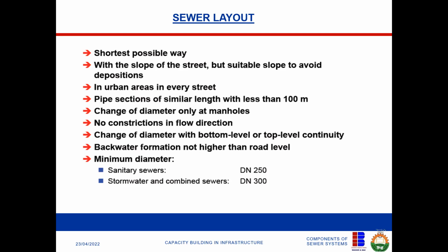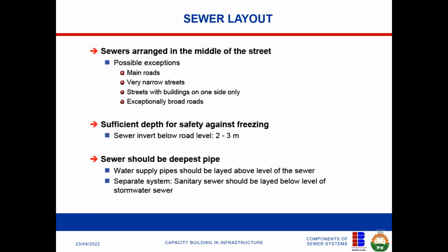You know, sewer has tissue papers, human remains, different nonsense you can find there. So you should make sure that anything that will lead to blockage must be avoided, and so on. Then you must make sure there's no backwater formation, and so on and so forth. How do you arrange it? What is the depth for places that have snow? It should be not less than 2 meters. Here in Nigeria, 1.2 meters is enough because we don't have incidents of snow.